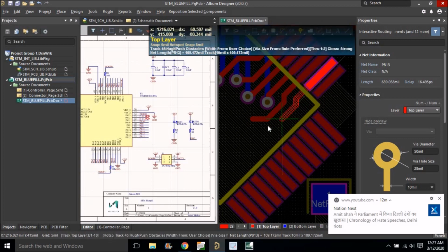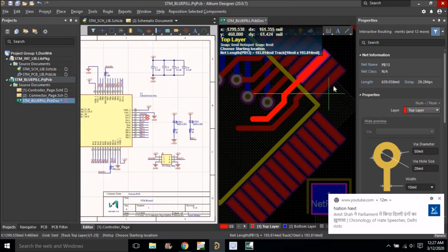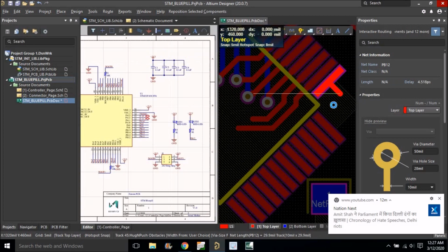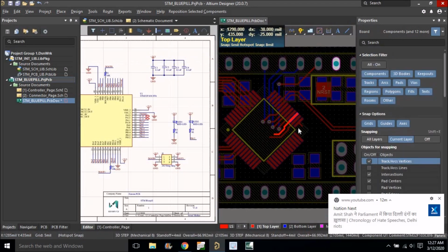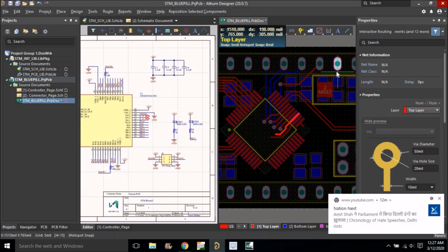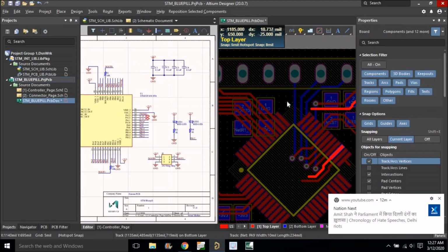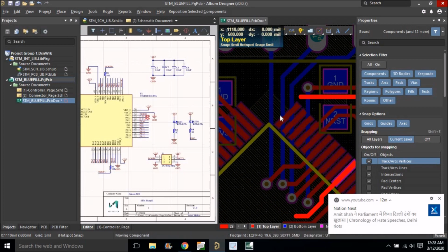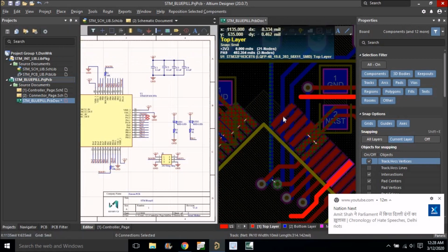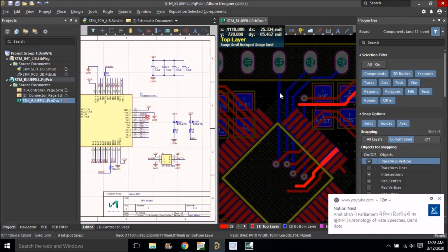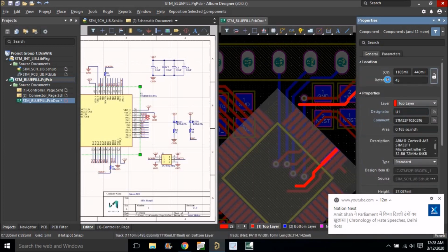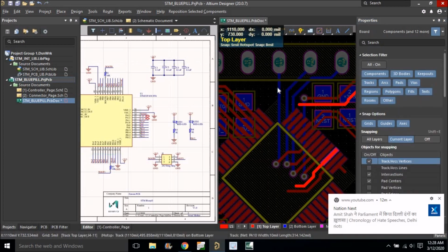These will also be like this, and this can be here. So firstly it will be the top layer. I just shifted it a little bit, sorry, Control Z, because I shifted the IC. So select the IC and lock this component so it can't move without our permission.